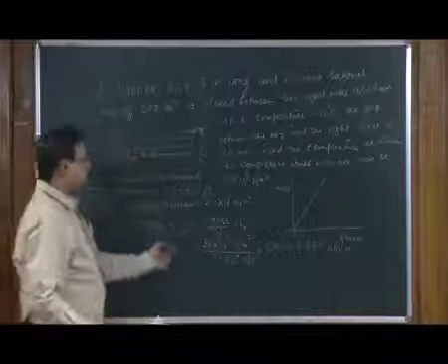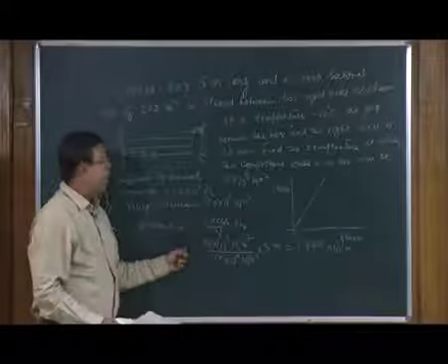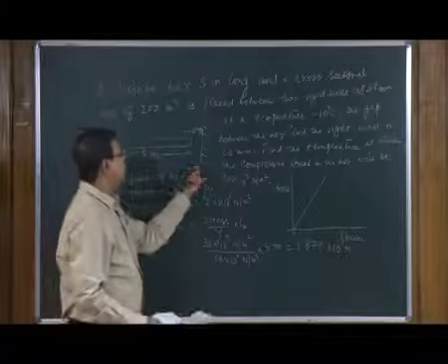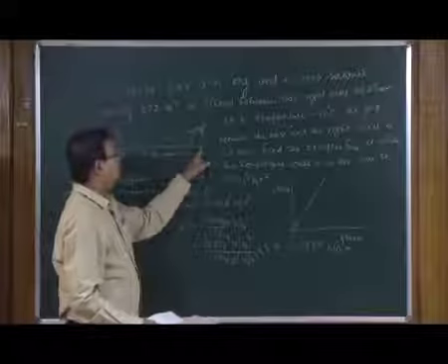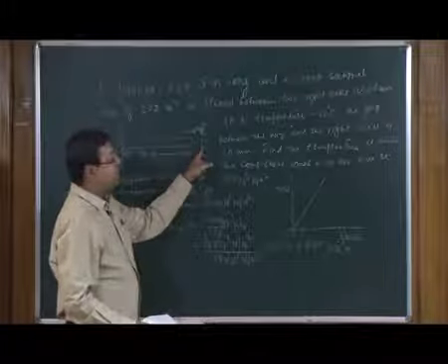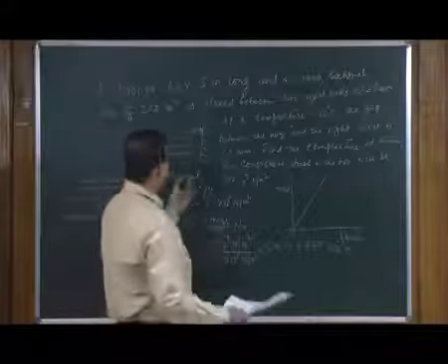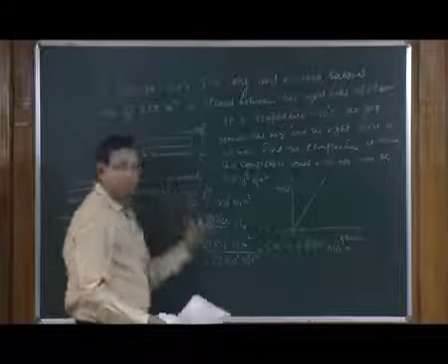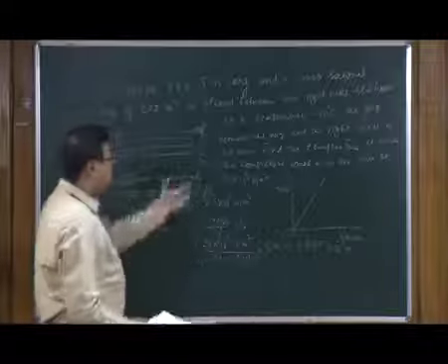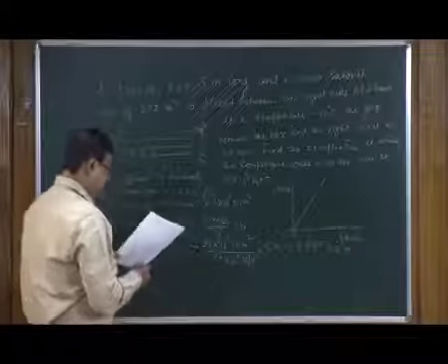Understand that this is the extension which will happen when the rod has expanded by this 20 millimeter, and because of the thermal effects it will try to expand even more, and there will be a compressive stress that will be developed.